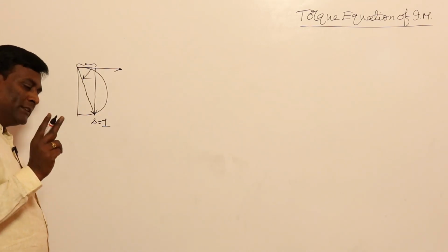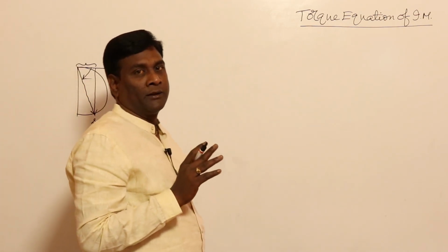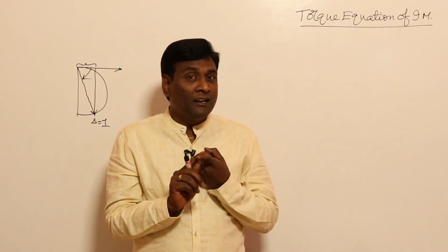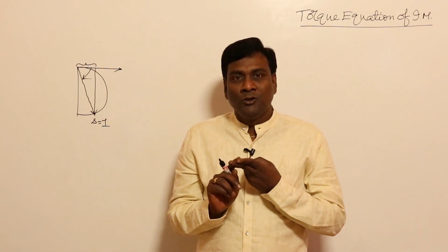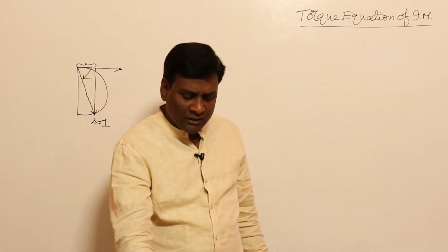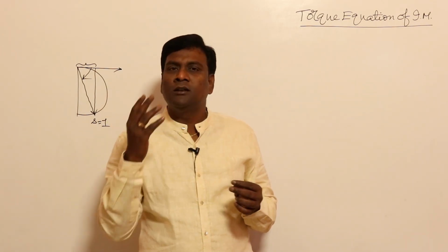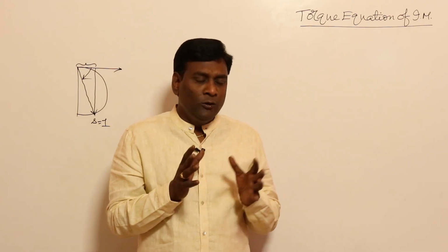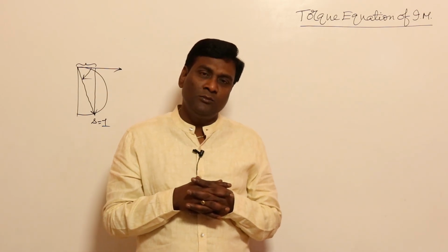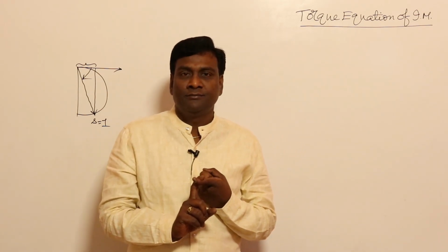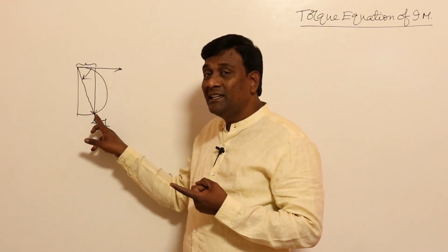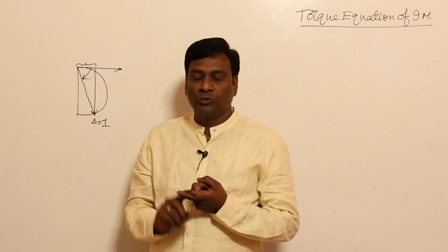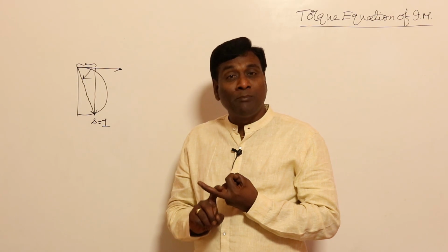So there are two disadvantages in a primitive induction motor. What are those disadvantages? Very simple: starting currents are high, starting power factors are less. So apart from torque speed characteristics, we have to remember those. In no other motor do we focus on this, but in induction motor we focus on starting currents. How the magnitude of current varies from S equal to 1 to S equal to 0 has to be analyzed, because starting current magnitude is more, and starting power factor is less.